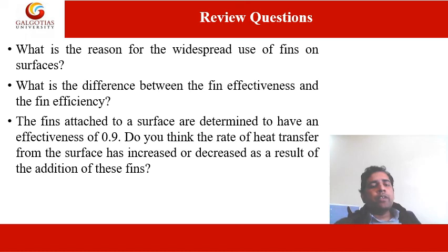Then the third question: fins attached to a surface are determined to have an effectiveness of 0.09. So what do you think, has the rate of heat transfer from the surface increased or decreased with the addition of these fins? This is a question related to effectiveness, as you have earlier studied. We have also studied efficiency. So you have to justify whether the addition of the fins has resulted in any benefit or not.